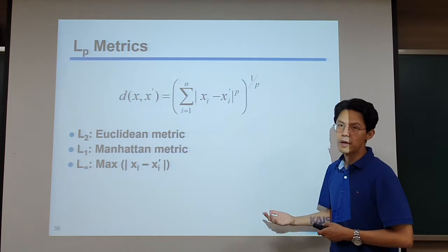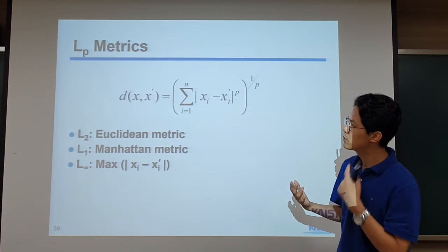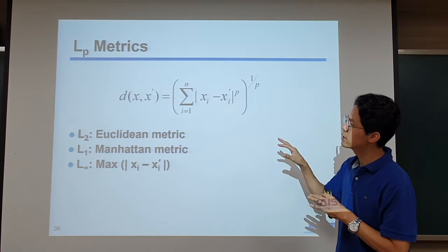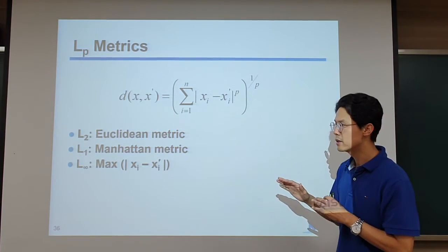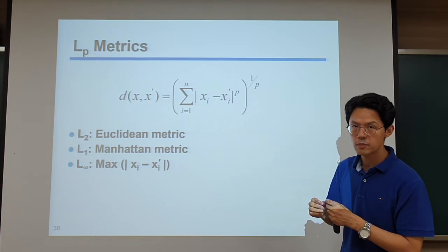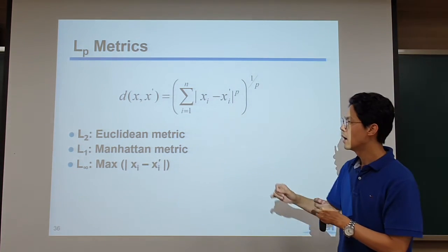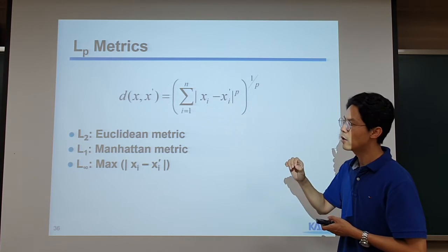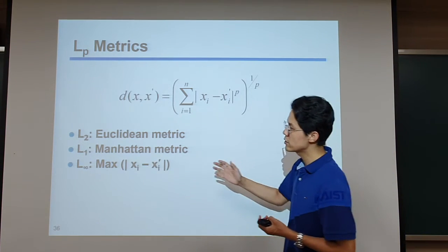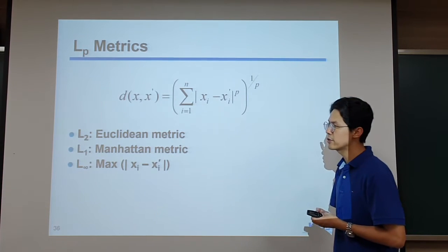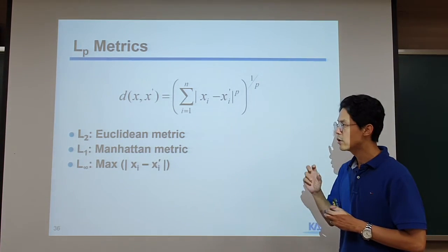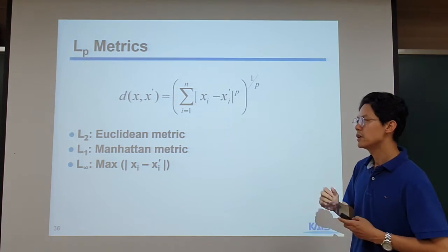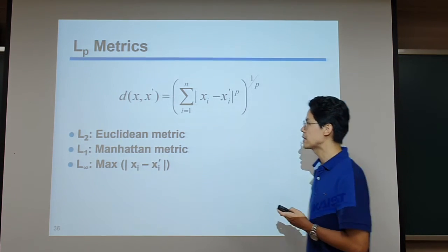Later on we will use this concept a lot. Basically, we need the metric to compute the distance between two points for computing the path, right? So depending on the metric that you are using, the performance of our motion planner varies a lot. Typically, we use the Euclidean metric a lot, but depending on your domain and your specific problem, you need to carefully choose this metric. But if you don't have a clear idea, you can start with the Euclidean metric.